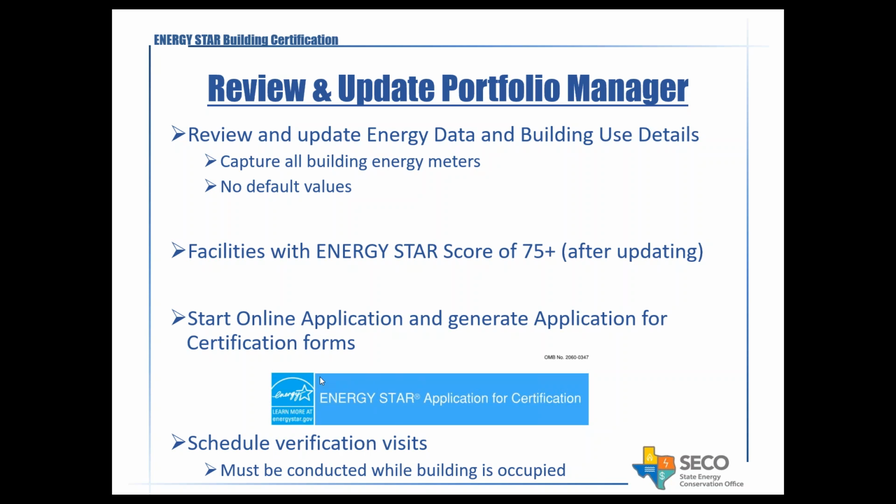So the top of an application for certification should look something like this at the top of the form. And then after you start your application, you'll need to schedule verification visits by your licensed professional, whether that be a registered architect or a professional engineer. And one caveat is that the site visits for verification must be conducted while the building is occupied. So for schools, unfortunately, summer might not be the best time to do it, unless there are summer school activities or there are building occupants there at the time of the site visit. And that's one of the requirements by Energy Star.